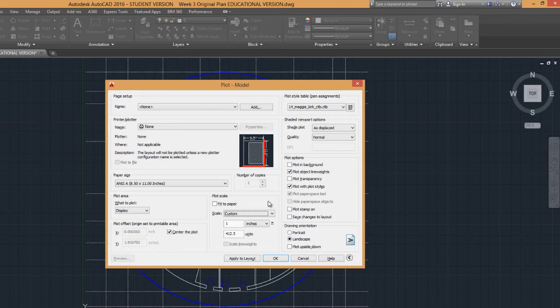not to be confused with the same layer, plot out with the same line weight. That line weight is simply a value given for the thickness of the line. Think like your different types of pens when you hand draft. So additionally, a CTB file is a separate file, so it's not an AutoCAD file. It's not a drawing file, but it's a support file. And much like the template file, we need to load a CTB file into AutoCAD in order to use it.